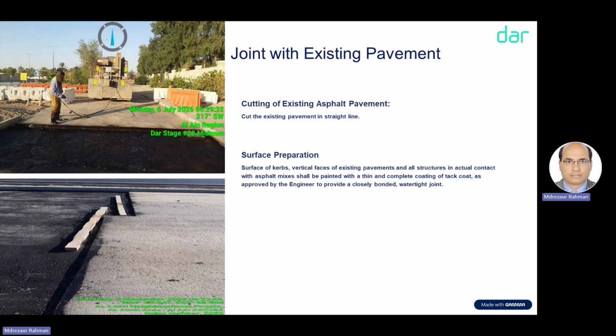Engineer, we are making overlap for the road base and the... Oh, this road base is different. Okay, this is different. For example, for the road, it is ADQCC. If there are road base joints, at the same joint we cannot do asphalt. It should be, I believe, 2 meters. 2 meters straight.